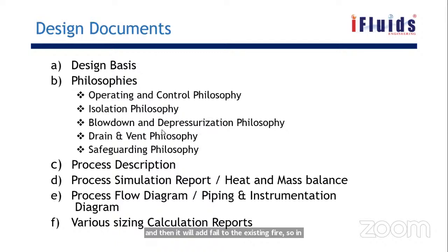So in case of any fire or any other plant emergency, or any major leak, they need to depressurize the system through a proper channel. Depressurize in the sense not to the open atmosphere; it will be a closed system. All those things will be captured in the blow down and depressurization philosophy. With this philosophy, we need to consider it for the design.